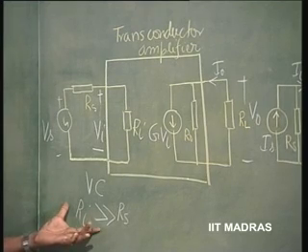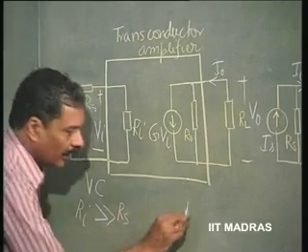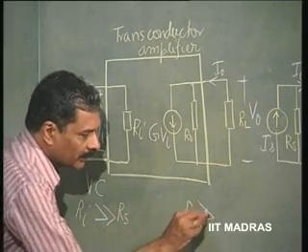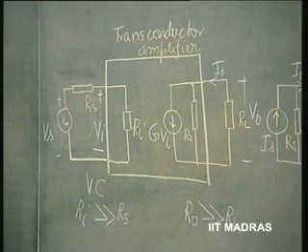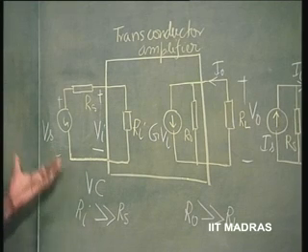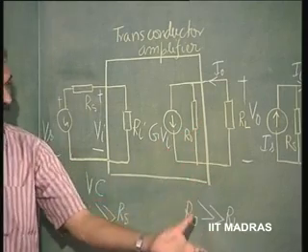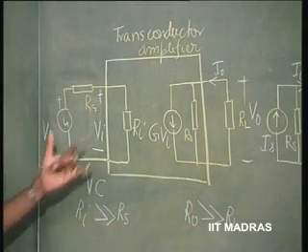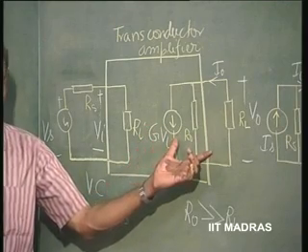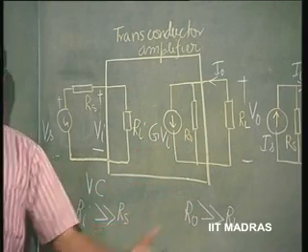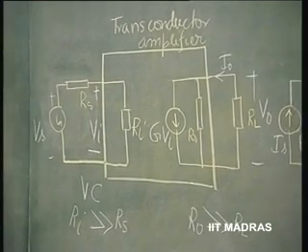That is voltage control. It is a current source at the output, that means R naught is much greater than RL. So, under this drive, with source impedance fixed like this and load impedance fixed like this, or when input impedance is suitably chosen such that it is this way and output impedance satisfies this condition, then we call it a transconductor amplifier.